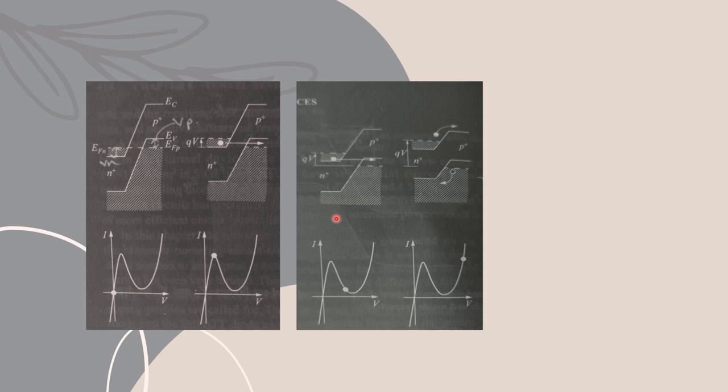When a forward voltage is applied, there must exist a common band of energies in which there are filled states on the N side and unoccupied states on the P side. The electrons can thus tunnel from the N side to the P side, and the energy is conserved, right?